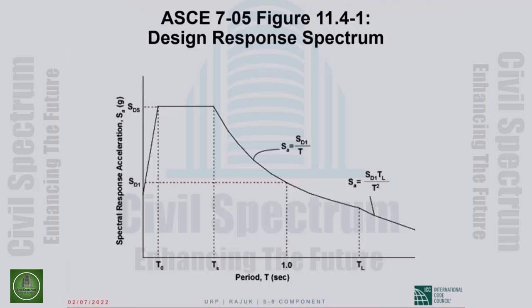Okay, so this is the design response spectrum, as it is called. That itself I will discuss not next week, but week after next. This design response spectrum, the concept of it. Anyway, this figure shows you the design response spectrum of ASCE 7-05. Spectral acceleration is on the y-axis. The period of the structure is on the x-axis.